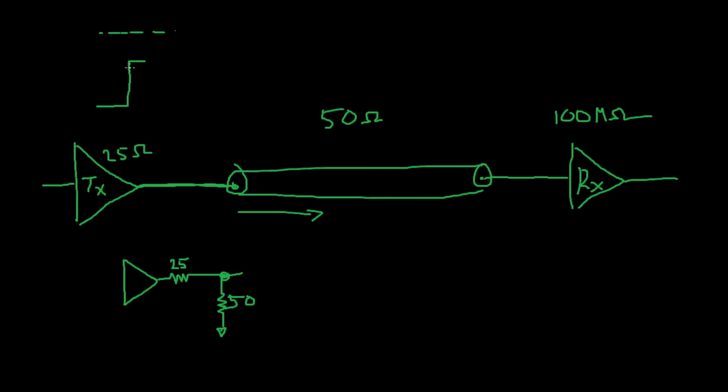But one of the things that happens when you see that reflection is the voltage over here, instead of being a step like it was over here, it's going to be a step that goes much higher than VCC. And the total voltage here is going to be 2 times the wave we sent down the wire. That's because it hits here and it reflects. They add on to each other.